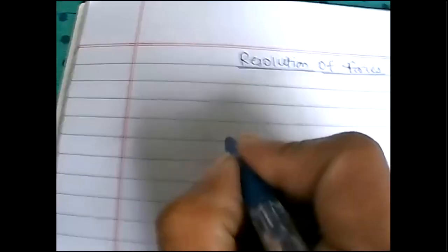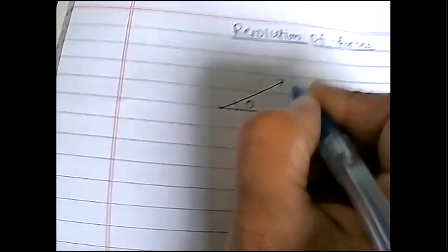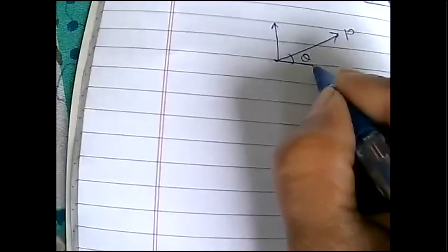Please look at this screen. I'll tell you how to resolve force. Resolution means what? First of all, I'll tell you. If one inclined force is acting on the body with some inclination, say its magnitude is P and its inclination with horizontal is theta, then what will be the effect in this direction and in this direction we are going to learn. So this component will be nothing but P cos theta and this will be nothing but P sin theta.